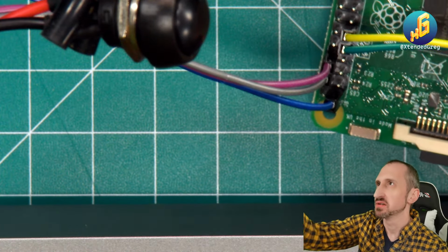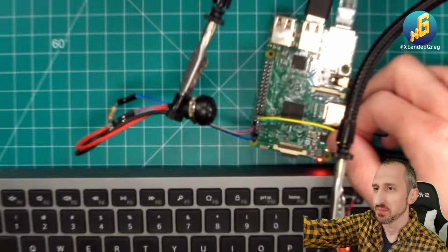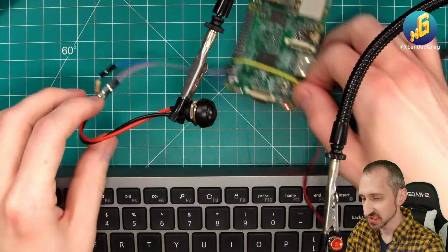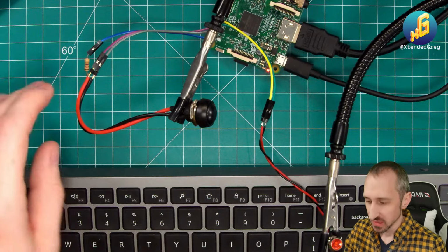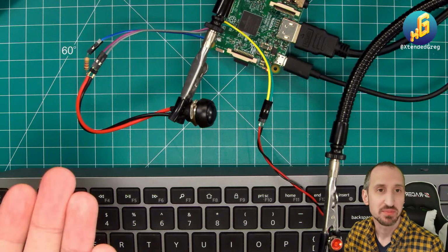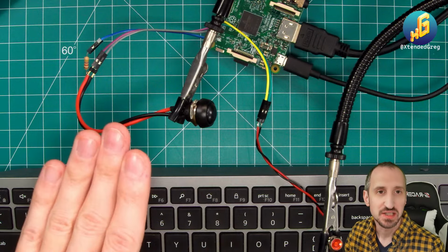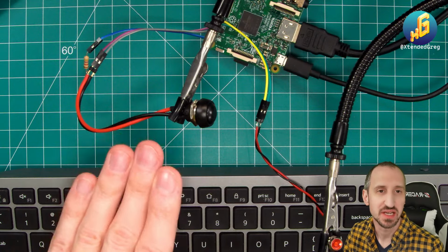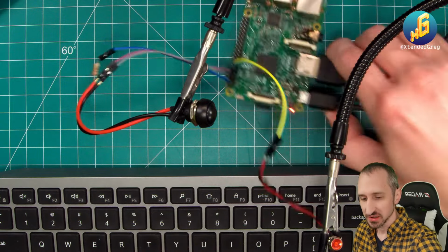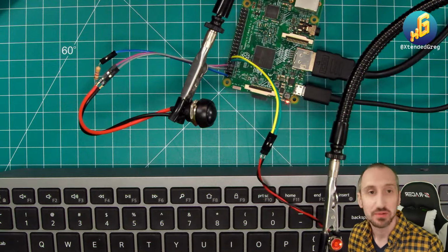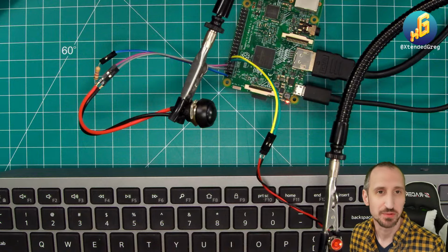But what it's doing is acting to pull up the pin. So when the button is not depressed, this is a normally open button. When it's not pressed, it's going to bring the pin high, and when it is pressed, it's going to ground out that pin and make it low. So we're going to show you how to actually go through and read that, but we also have the ability to disconnect it in case we want it straight through.